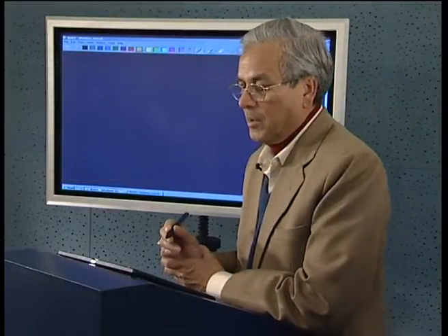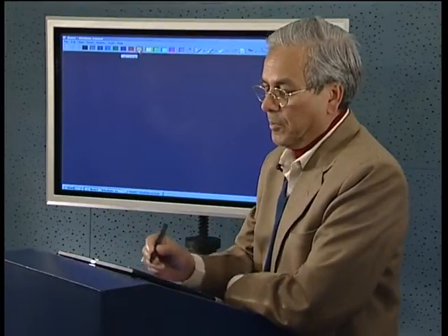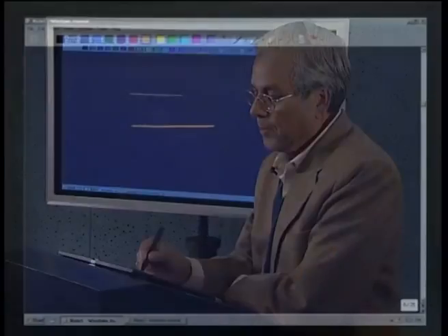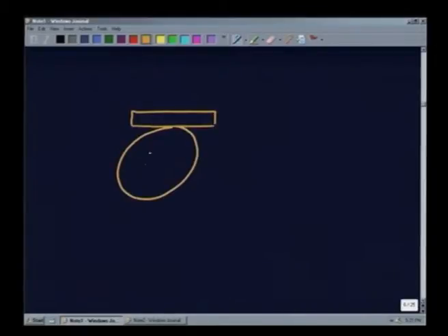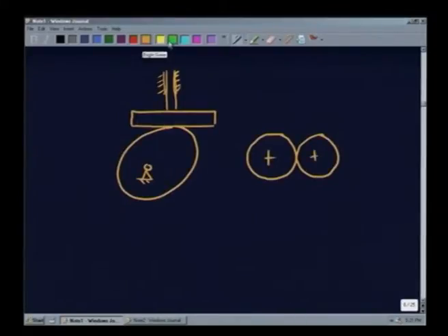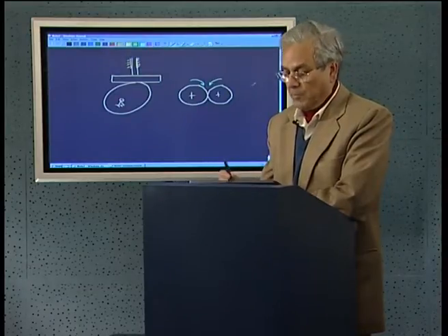Now, let us come back to our study of plane motion, primarily because a very large number of engineering systems undergo parallel motion problems. As for example, we have shown our slider crank mechanism. Even if we take a simple crank follower mechanism, here again we will see that all particles describing this system undergo motion where the velocities, displacements and accelerations lie in parallel planes. We can have motion of a gear or a wheel transmitting power between two shafts. Again you will find that all the points undergo motion where the motion parameters lie in parallel planes. So, there are a very large number of engineering problems or systems which involve plane motion, and so let us first start studying the problem of systems involving plane motions.